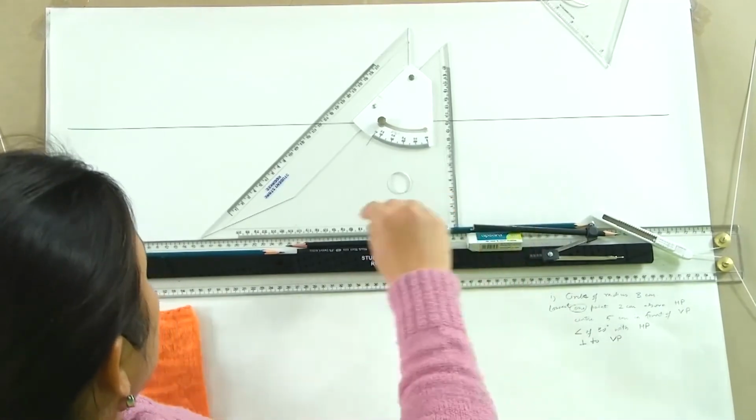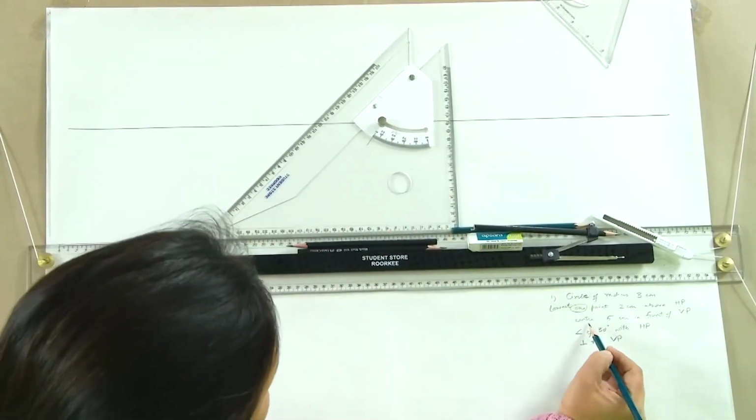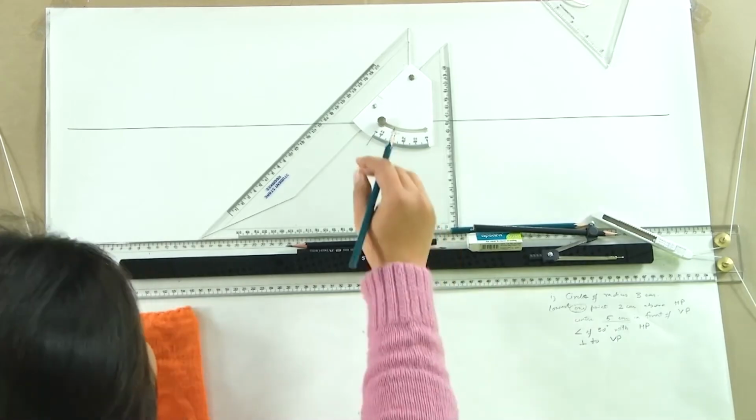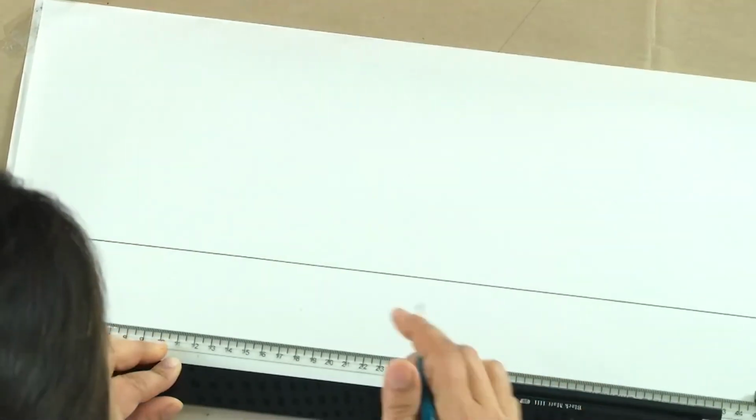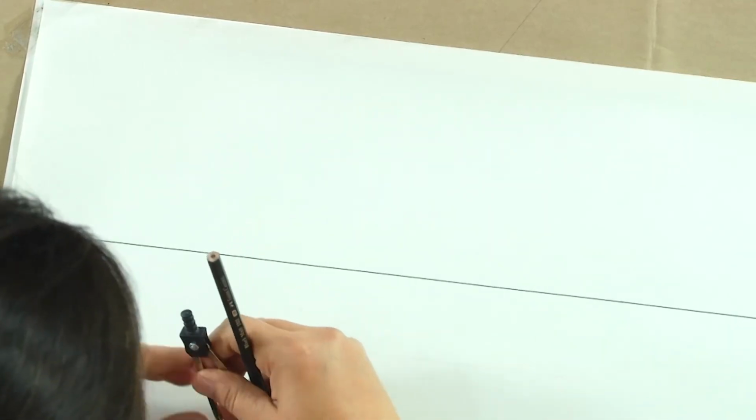Now to start with, we will have to determine where the circle is. What it says is that this circle has its center 5 centimeters in front of VP. So what do we do? We just draw a line 5 centimeters in front of VP. So it will be seen in HP. This is the line where the center of the circle is going to lie. Now this circle is of radius 3 centimeters. So we take 3 centimeters